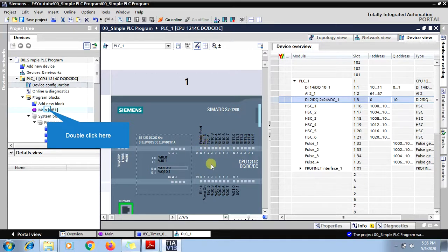If you closely observe, if you are viewing this project again and again, you could see that I have given the name of the first digital input as pump start, and the first digital output is blink, the second digital output is pump on. If you are first-time viewers, I will just change and show you that this is my first input. Its address is 10.0.